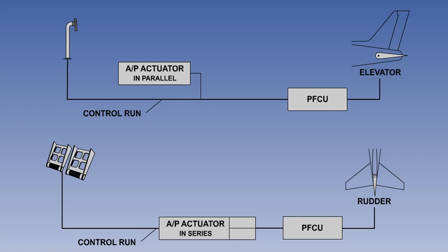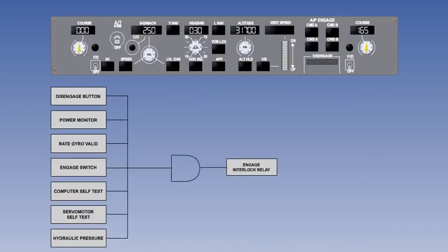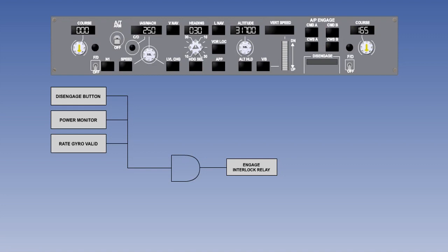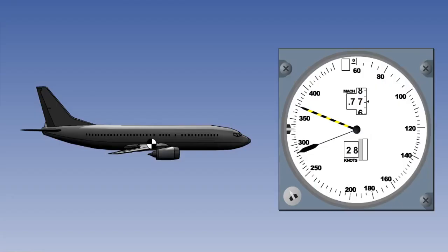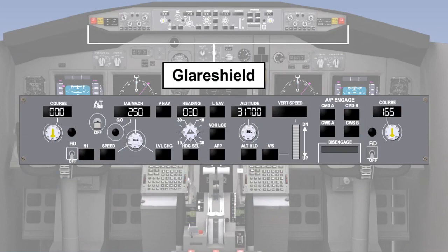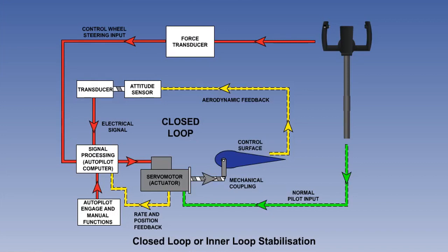During this lesson, you have learned how the autopilot moves the aircraft's control surfaces, the interlocks that have to be made before the autopilot will engage and remain engaged, and the reasons it will disconnect. Next, you are shown AutoTrim, which is an autopilot function, and MachTrim, which is not an autopilot function. And you studied the pilot-autopilot interface, the mode control panel. Finally, we considered the control wheel steering, which allows the pilot to use the control column to control the autopilot.